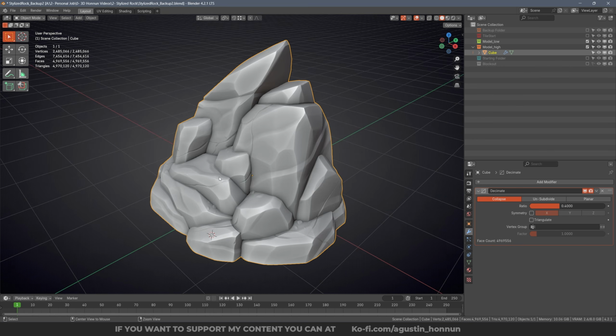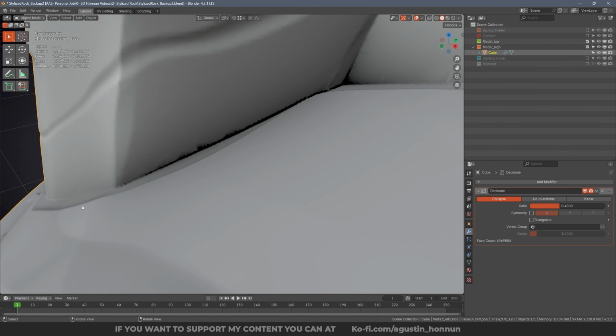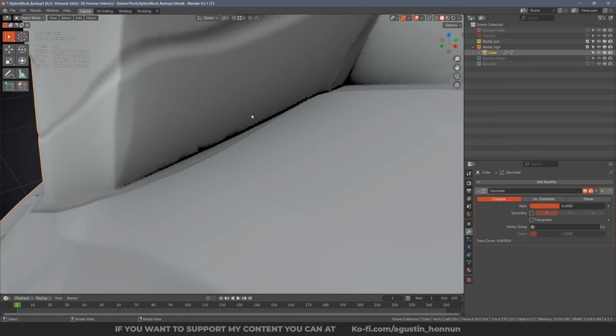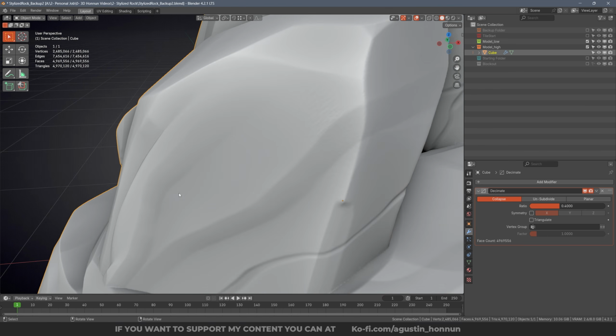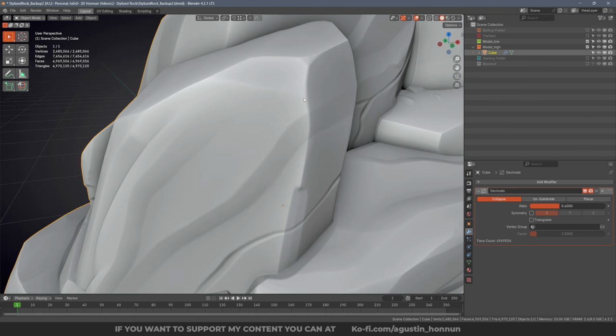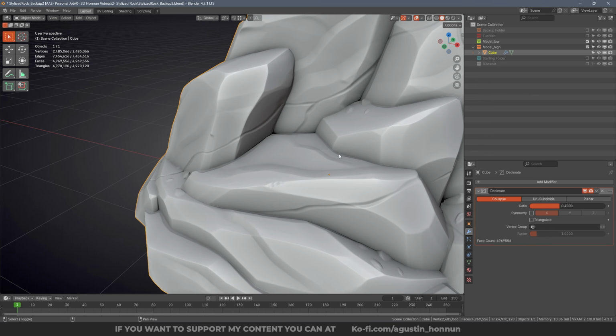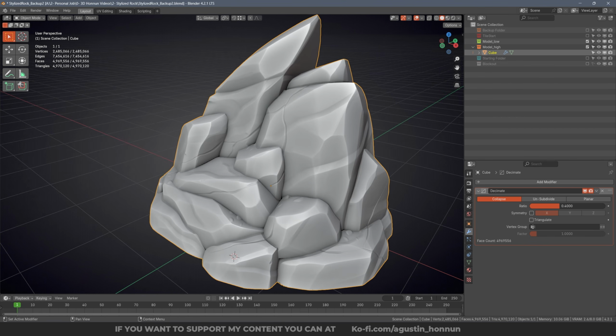You can keep it like this if you want to remove those shading problems later in the normal map using Photoshop or any other software, or simply continue increasing this value until you don't see them. But of course, you are going to be increasing the triangle count again.